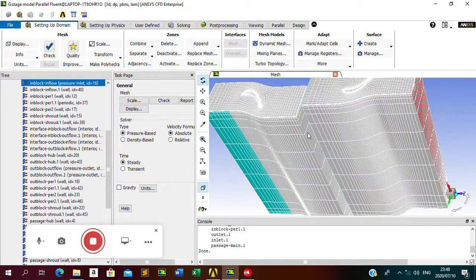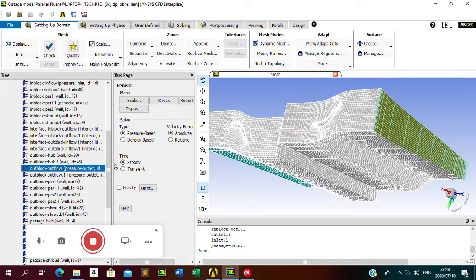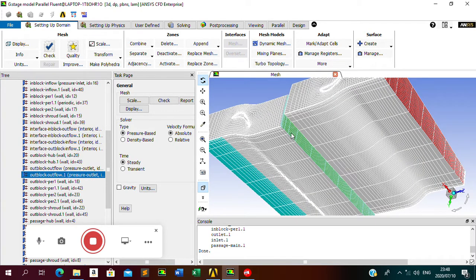So I have my pressure inlet, I have my pressure outlet. This one says pressure outlet, which is the other boundary. This one says wall. Maybe these two are not really required to be pressure boundaries. The ones that are required to be pressure boundaries are these two, the interface ones. So this maybe could be something else.